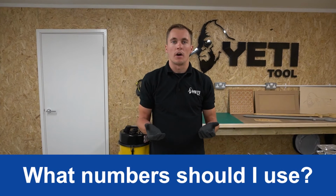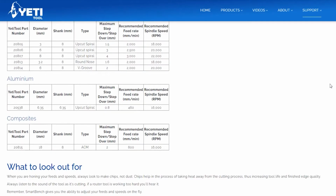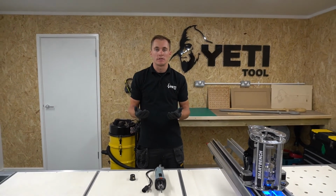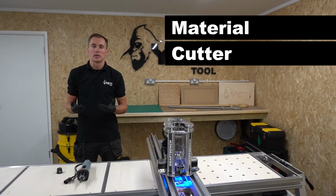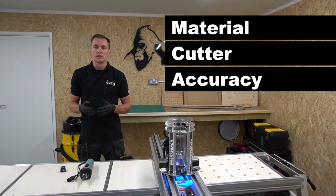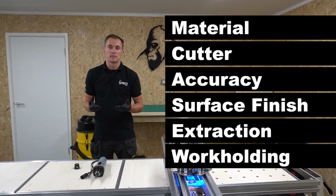What numbers should I start with? We've put together a list of recommended feeds and speeds to get you started. These can be found on our knowledge base. We'll post a link in the description below. Remember, these are just a starting point. There are many factors that can have an effect on your feeds and speeds. For example, your material, your cutter, including the type, the material it's made from, and the sharpness, your desired accuracy, your desired surface finish, extraction performance, and your work holding techniques.